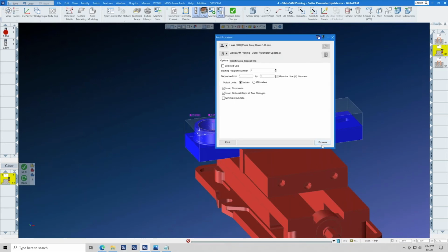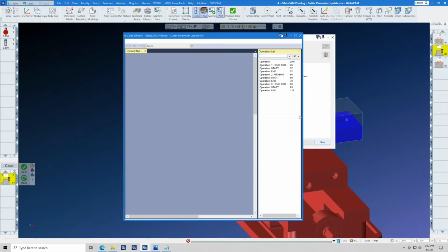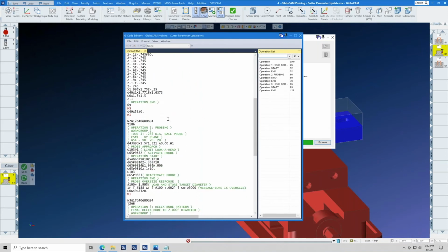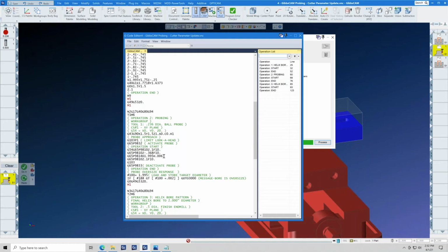Now, we're going to have to go back over that again because it requires a little bit of explanation. Semi-finished pass, probing. We probe the bore, but as you can see here on the end of the 9814 line, there is no S value. The S value would normally set a work offset.